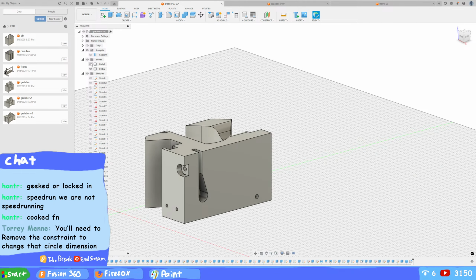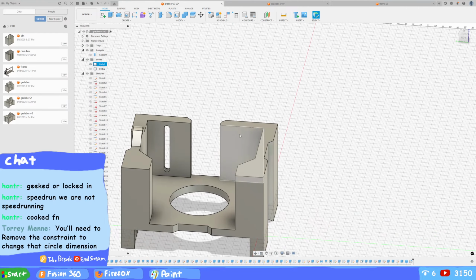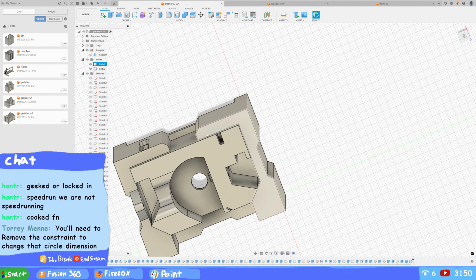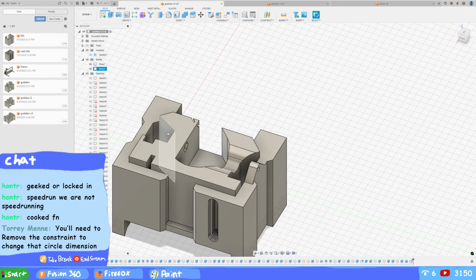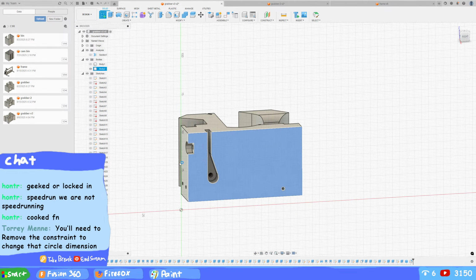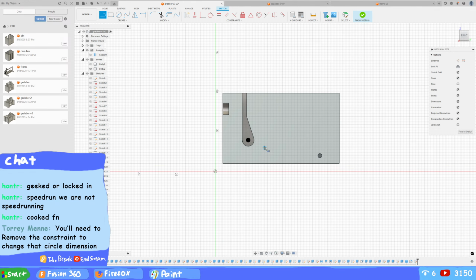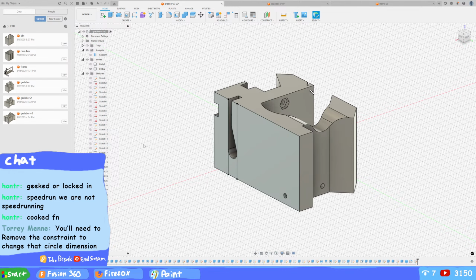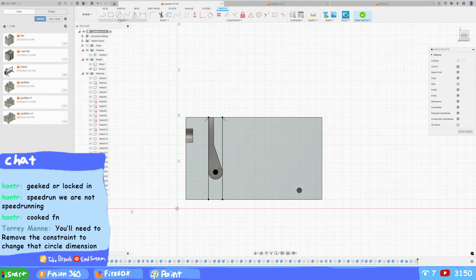Oh, right, that reminds me. I need to go into here and cut, and I need to move this in a little bit. Not that entire thing, but I need to make it so that the screw here does not, because, like, okay, here, this is all we need to do. Create the sketch, and then we create 2 lines, just anywhere and anywhere. And that one's fine. We get tangent this to this, finish the sketch, and then we actually need to go back into that sketch. I need to make this be a rectangle.